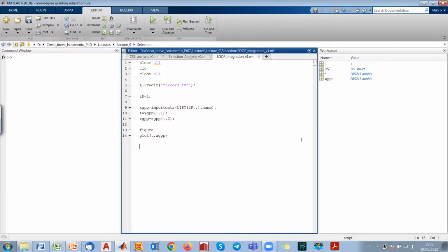So let's start with the curved surface slider, which is the easiest one, because we have to define the friction coefficient equal to 5%, and then the equivalent radius of curvature, which is equal to 3.16. Then I want to show some particular strategies for that. So Vs equal to 0.0075. And I think that's it for curved surface sliders.